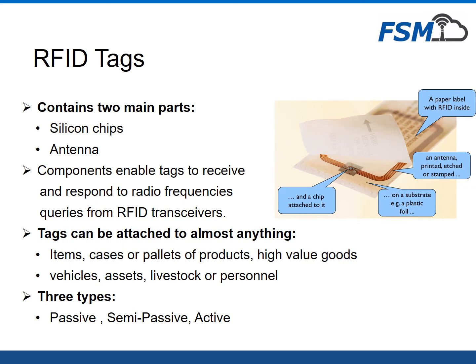All these are pre-engineered, and different tags with different geometries can give different range of reading with the same readers, or different speeds with which data is read, or different speeds of movement of the tags. Generally speaking, the larger the tag, the better the sensing distance, the bigger the size of the antenna on the tag.